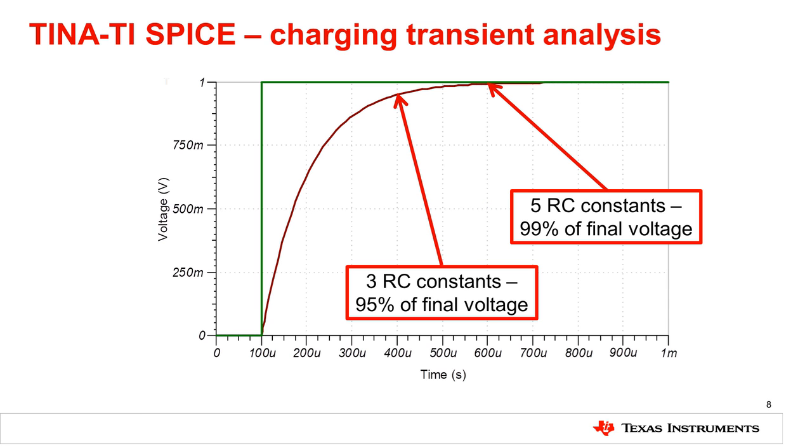We can now see the transient response of this circuit for a 1 volt step function. For this simulation, we used a resistor of 10 kiloohms and a capacitor of 10 nanofarads. Multiplying these two together, we get a time constant of 100 microseconds. From before, we know that a charging RC circuit should reach 95% of its final output voltage after 3 time constants. To find this point, we take the beginning of the step function at time 100 microseconds and add 300 microseconds.